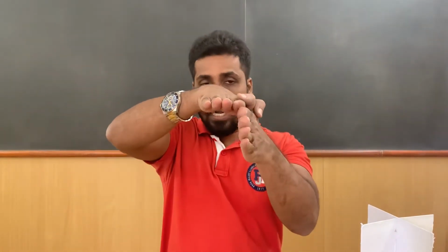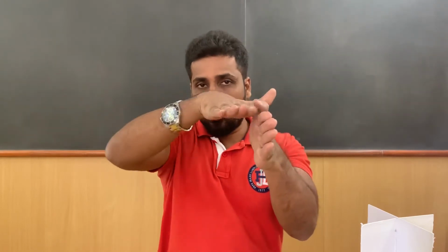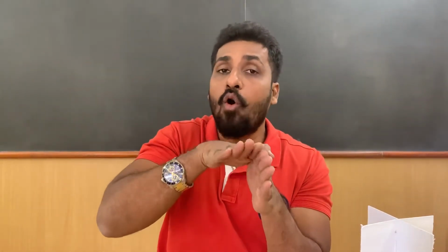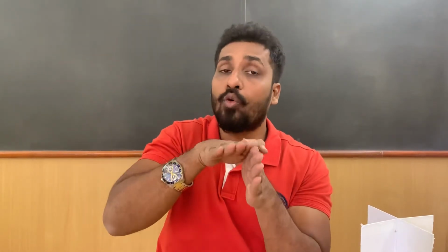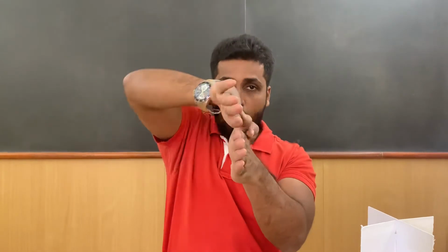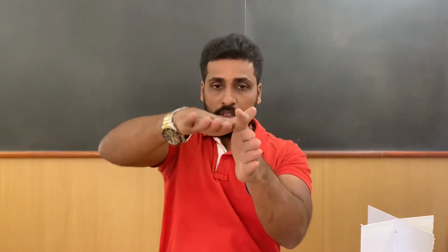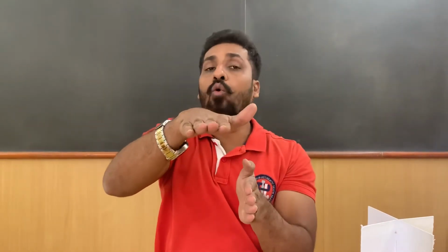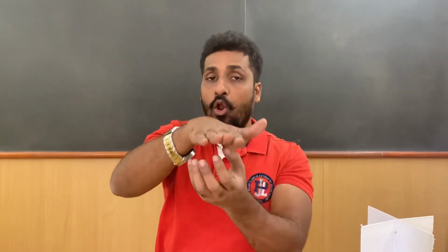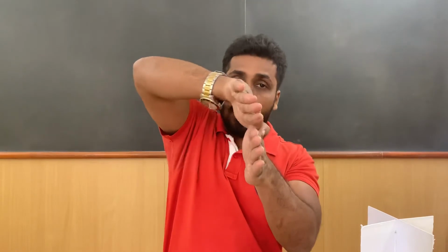Let's talk about the third quadrant. In the third quadrant, that was my position of the third quadrant, that's the horizontal plane, that's the vertical plane, and again I am telling, only the horizontal plane can move, it can rotate in the clockwise direction. So you take the planes, you rotate the horizontal plane in the clockwise direction, so this is how it is going to rotate. So we know that the top view is always associated with the horizontal plane and the HP has gone above the xy line.